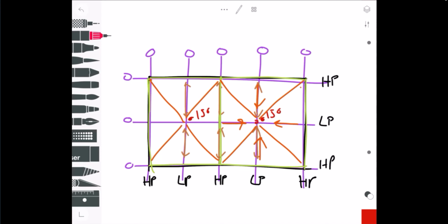That's not always the way our buildings are, but that's the approach of how to see if it's possible to slope your roof structure. A couple other things I'll just say with this is that, you certainly don't want to just have one roof drain on a building. So let's just say if your building was this right here by itself, you always want to have secondary